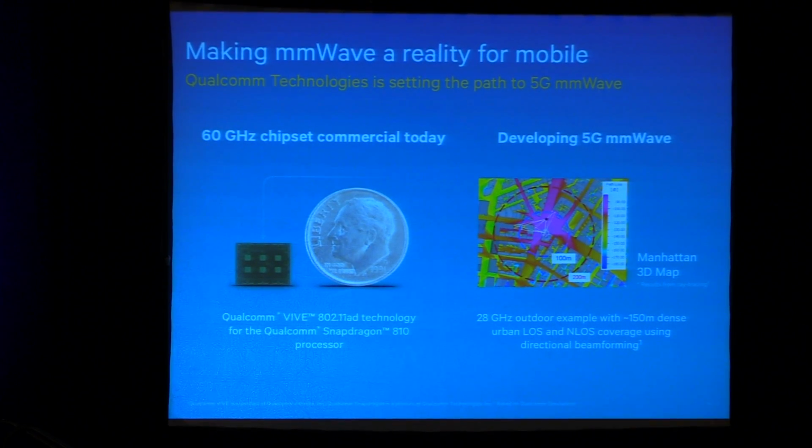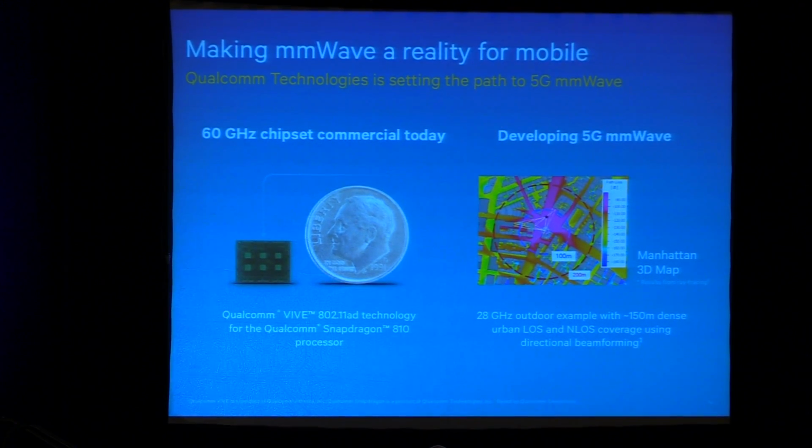The picture there is from our 802.11ad technology, which is the 60 gigahertz Wi-Fi, and that little green thing, it's about half the size of a postage stamp, has 32 antennas on it. They're little dipoles. You can see them there around the outside. They form beams on both sides of the link. The access point forms beams.